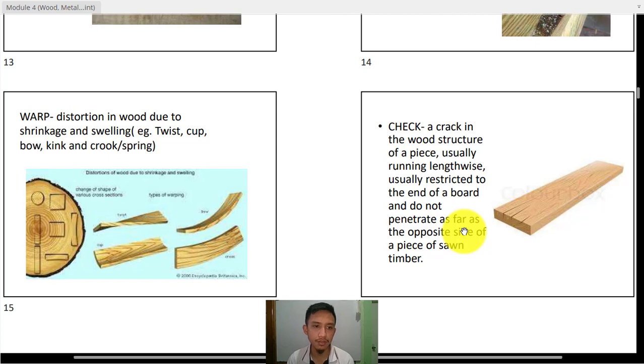And if you consider designing, we should have a material that has a predictable property so that we can incorporate that in the design. Okay, that's why in big construction, maybe we will be using this as part of divisions or even trusses. We are only using wood as part of trusses in small constructions, let's say just a house, or just a bungalow type. But in high-rise buildings, we are not using wood as a structural member.